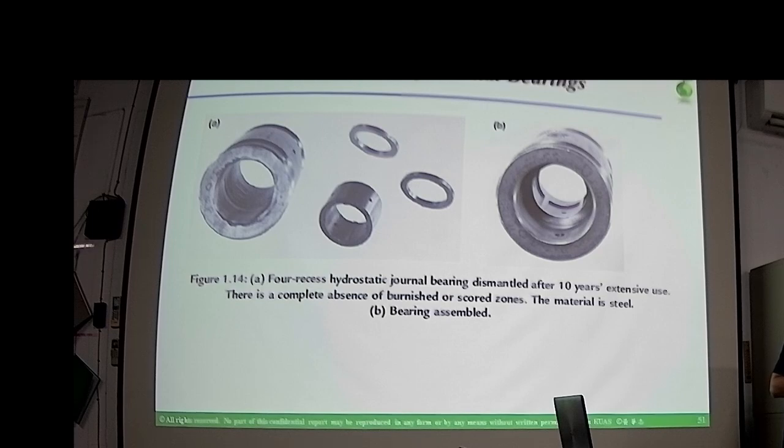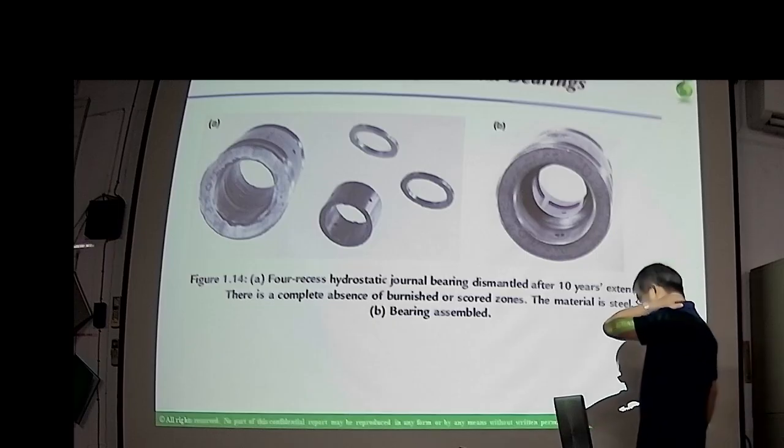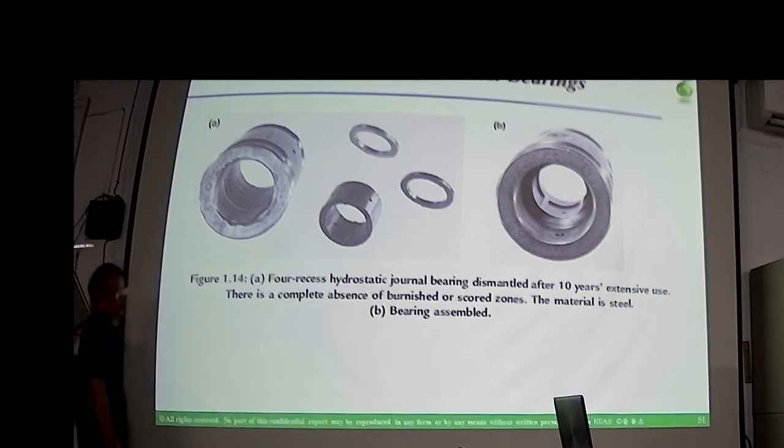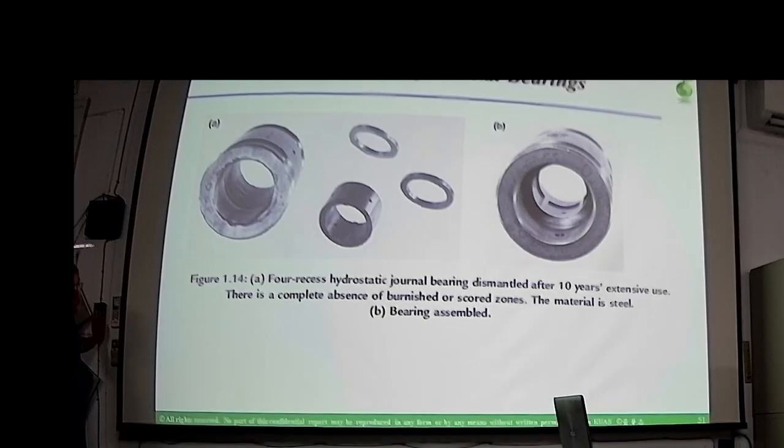So therefore, you should have a guarantee for long service life without wear between the bearing surfaces. 通常好的静压轴承设计的话，它工作起来是完全没有接触，所以其实不会有太大磨耗的问题。One German company, once we showed you, called Monforts, they have a guarantee for the hydrostatic bearing product from the turning machine. 5 year guarantee, no wear.